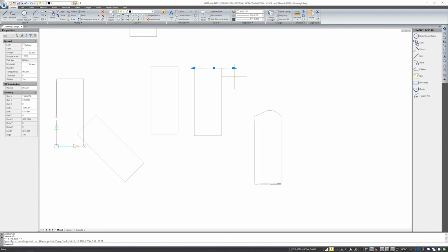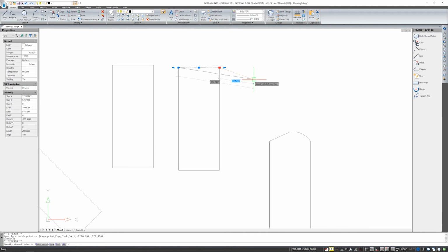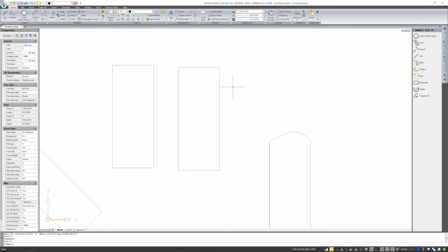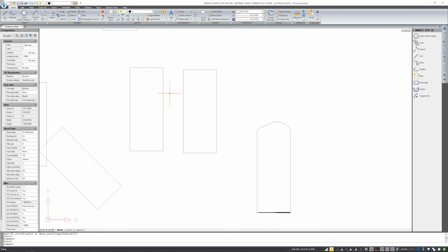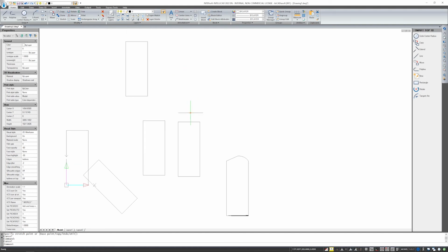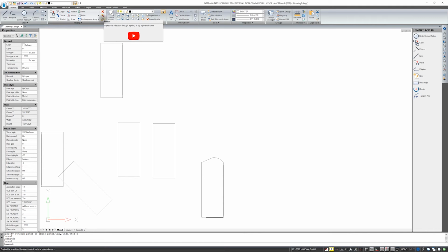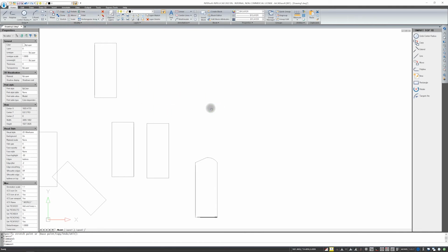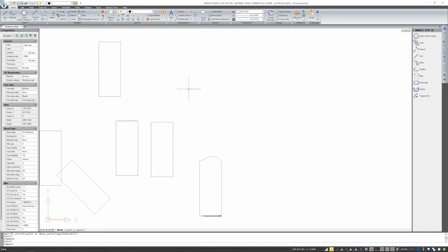If you want to keep an angle, if you use these triangles at the beginning or at the end, you can shorten or lengthen this line accordingly at the existing angle. If you grab the square handle, then unfortunately the angle will no longer be maintainable. Of course, the stretch option will give you such an opportunity, while you can simply select and lengthen the line using these triangles. Besides, if you were to continue drawing the documentation and use such an option as, for example, offset, then the line will behave a bit differently. And of course, your polyline will also behave differently, which I will show you in a moment.